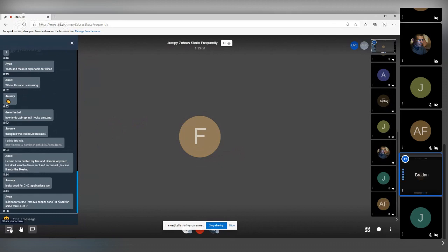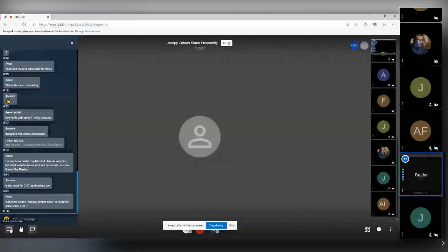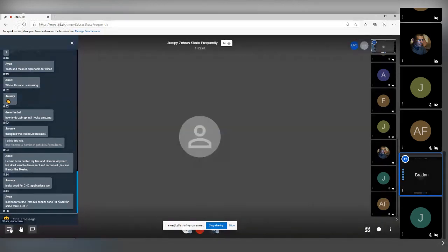The challenge I have is when you start doing 10 LEDs, then you've got to create 10 unique keep out zones in the PCB. And if you ever move an LED, then you've got to move that around. So while it's a better result than the kludge that I use of putting a tiny dot and then a big offset on it, at least with that I can move things around, and I can create a new printed circuit board and just drop 10 LEDs on it, and everything's working for me.